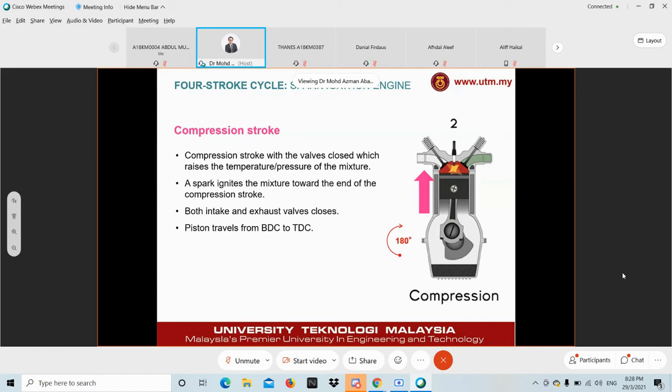When the piston starts to compress the air and moves up halfway, the pressure and temperature are so high that they trigger combustion by themselves without the spark plug's assistance. So the combustion starts earlier, and usually